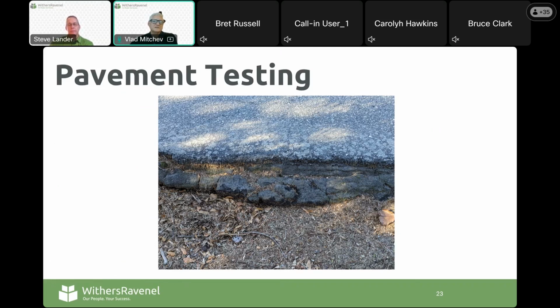What else can you do here if you have 7, 8 inches of asphalt with no aggregate base underneath? We'll talk about this a little later, but it is pretty expensive to mill and remove the entire asphalt, and there's probably not even a very good reason for it. Even if the cracks go all the way through, there are some other ways to mitigate that.